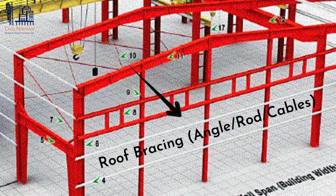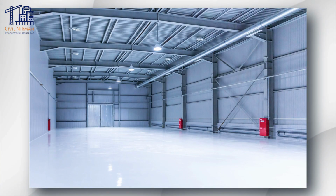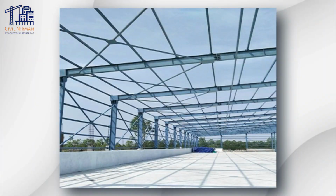On number 10 we have roof bracings. As our component number 7, bracings I have already discussed, but let me give you a difference between the elevation and roof bracing. See, elevation bracing is installed in the vertical plane, typically between the columns, to resist the lateral forces such as wind or seismic loads, ensuring stability along the height of the structure. While plan bracing on the other hand is installed in the horizontal plane, usually between the beams or trusses, to provide stability and distribute load across the horizontal surfaces, maintaining the structural integrity in the floor or roof plane.